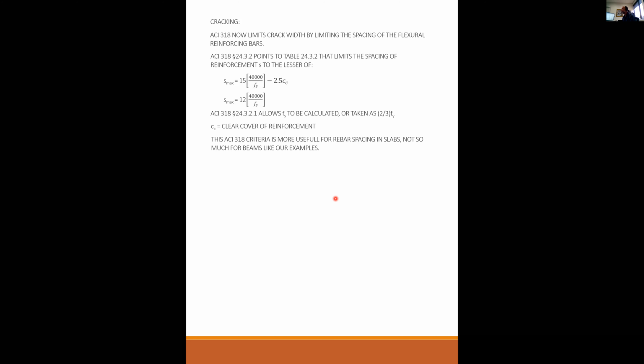But when you add the 2.5 inches below the steel that you need for the beam, now you're asking the builders, the contractor, to build you a 28.5 inch deep beam. And they're not going to do that.